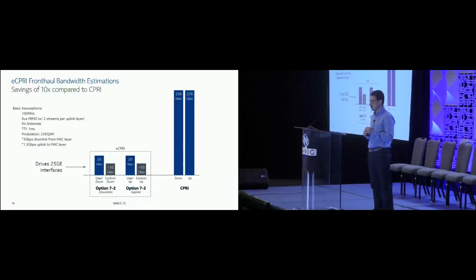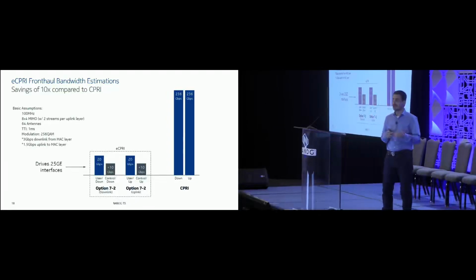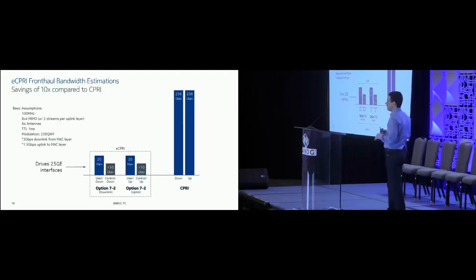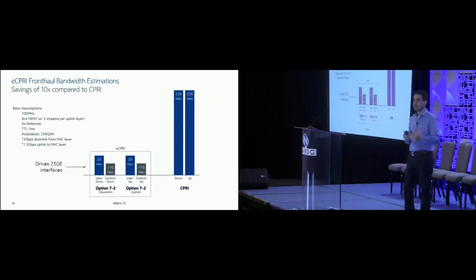So that's why whenever you think about Ethernet front haul, you better start thinking about how you're going to incorporate 5G Ethernet transport into your network, because 5G will require 25 gig interfaces, right? And this is specifically for the front haul. For the mid haul, for the time being, I think 10 gig is going to be good until we actually go to higher radio channels. And in that case, in millimeter wave, we might need some higher interfaces or higher than 10 gig.